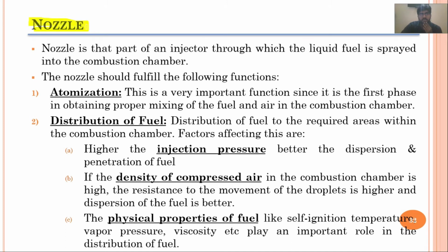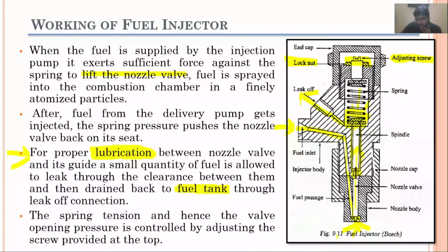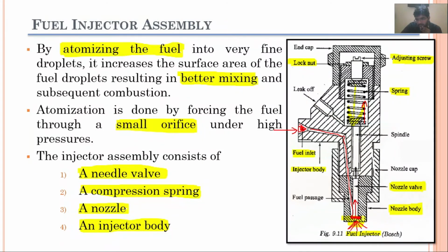So as I mentioned earlier, the nozzle is a separate part of the fuel injector and it has a very important role. Now we will discuss the phenomena which this nozzle is basically utilized for. The nozzle is that part of an injector through which the liquid fuel is sprayed into the combustion chamber. This entire component is our nozzle, and from this component fuel is injected into the combustion chamber.